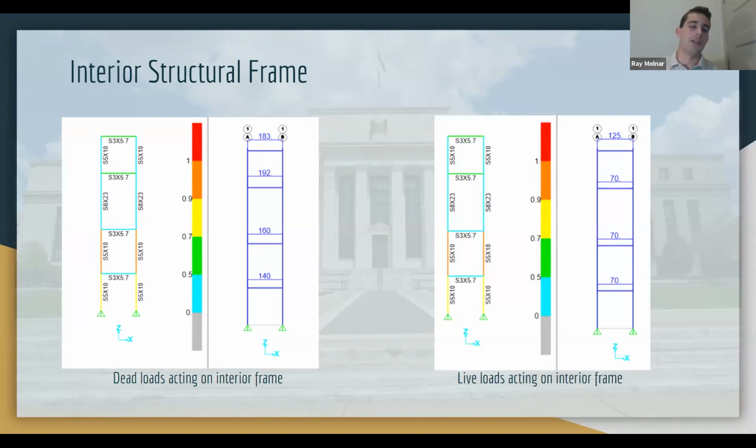I think it was the combination of those loads on the top and the weight of those additional floors on top of those particular columns. It was fairly close to one. Ultimately, that was the sweet spot. Ideally, we would have all those beams and columns in that orange region, because that's where you optimize your costs. You don't overpay for oversized or over heavy duty beams, you know what I mean? So ideally, every beam and column would be in that orange region.